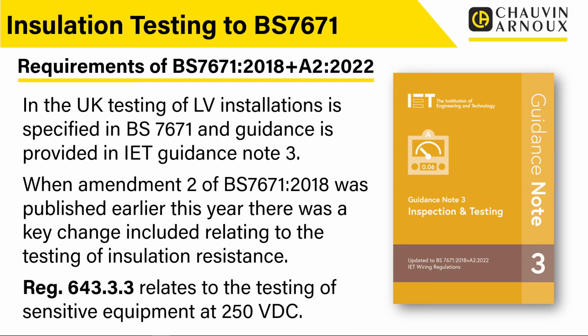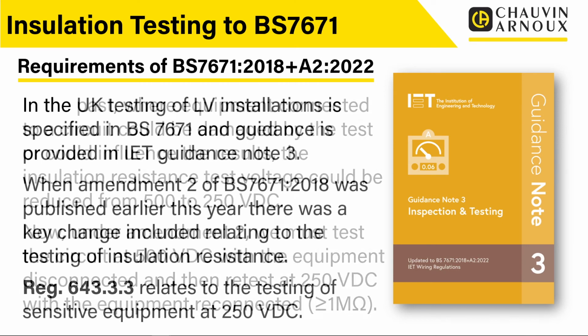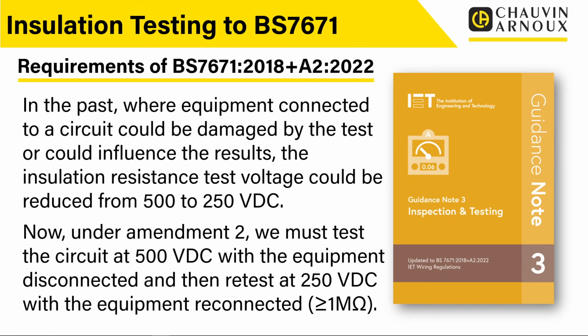So Regulation 643.3.3 relates to the testing of sensitive equipment at 250 volts DC. That's the specific bit that's changed. This is the nuance that's come into the testing. So let's have a look at that in a bit more detail.